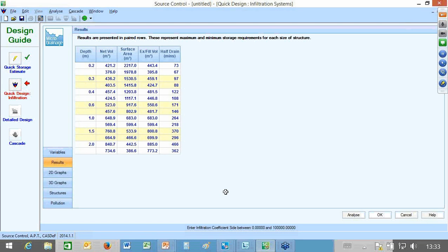Okay. In terms of evaporation, that would be the impermeability factor. You would reduce the 100% runoff. So if you had 2% evaporation, 11% evaporation, that's a potential to reduce that from the impermeability factor. Within the porous paving, you can add in an evaporation coefficient, or evaporation percentage rather. It would be something probably like 11% in the Middle East. So that would happen in the permeable pavement option because they're typically very, very shallow.